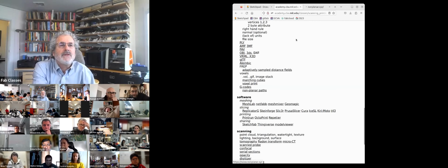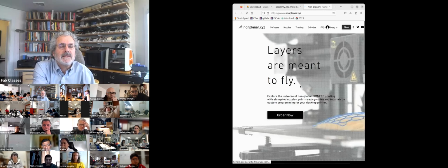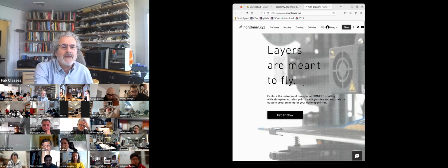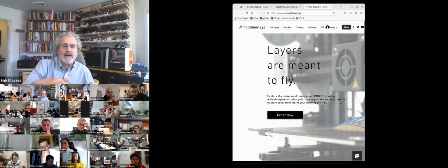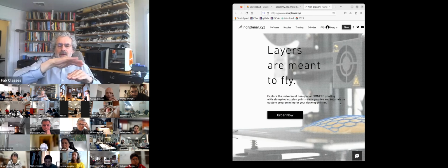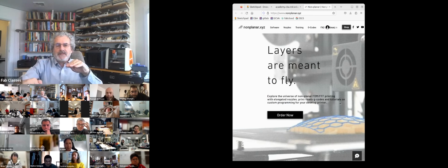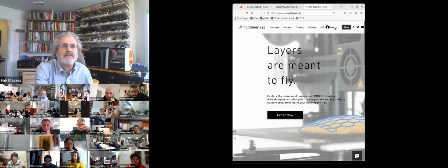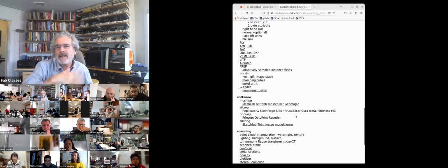But one of the things you can do with G-codes is you don't have to print in flat layers. And so something that's an emerging research area is by moving all 3 axes at once, you can make smooth surfaces and print more efficiently than just slicing in layers. And so non-planar printing is really still a research area, but it's beginning to get deployed.